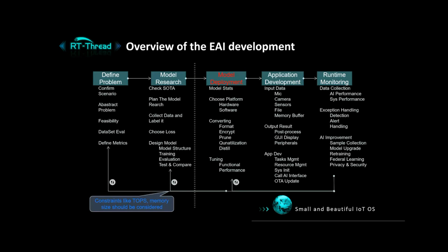So this part is mature enough now. There are so many talented people focused on this part. So the problem is the model deployment. This part is quite difficult so far because our device usually has quite limited computing power, memory and storage. So we cannot just pull the best model, the SOTA one, and put it on our board. For example, VGG16, I remember it is about 5 megabytes, just the model file itself. The whole board cannot contain that model. How can we use it?